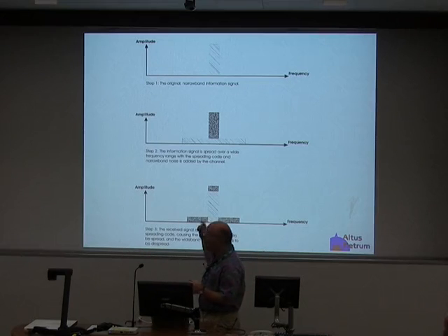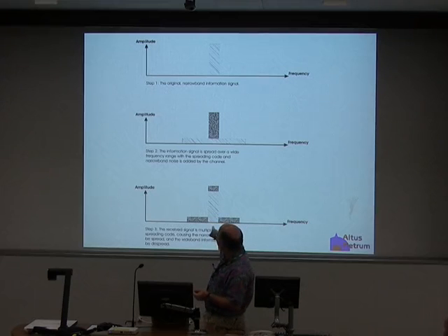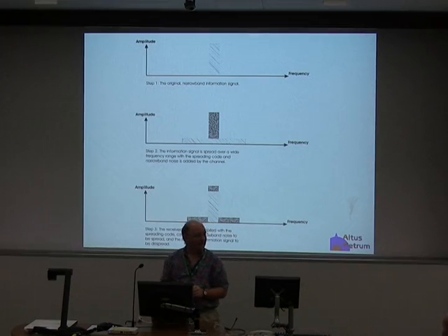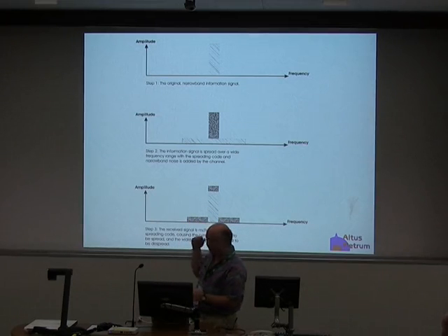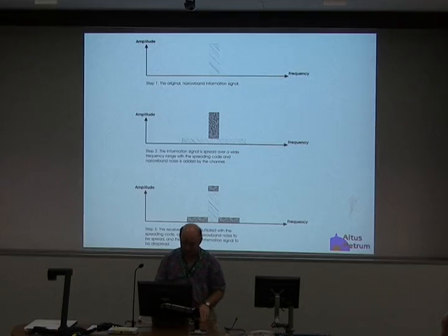What does it do to my original signal? I'm multiplying back in that pseudo-random sequence, which gets rid of all of that spreading and gives me only my low bandwidth signal again. And so I've got this huge amplitude of the signal and a very tiny amplitude of the noise. Kind of pretty awesome, huh? That's where the coding gain, the process gain in direct sequence spread spectrum, comes from.